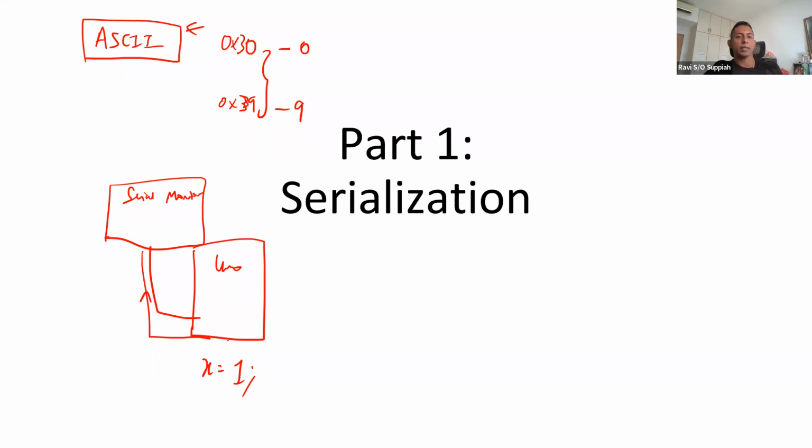So if I want to print 1, 0x31 is 1. If I want to print a 1 on my serial monitor, I need to make sure I do an add or whatever you want to do. So you can say x equals 0x30 OR with x, and then I will get the equivalent ASCII value. So x will now become 0x31. When I send it over, it will print out as character 1.